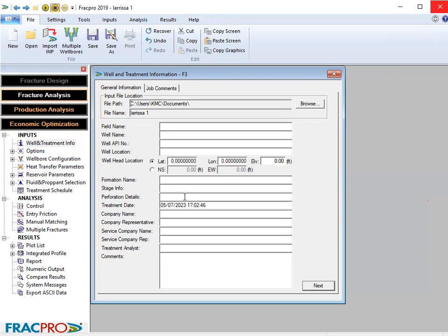Because under hydraulic fracturing well in Prosper, they'll ask you for the fracture height, the fracture width, the fracture half length, the fracture permeability, which will be part of the result that you're going to have. Once you generate that result, you see all of it indicated there. Once you have all of these parameters, you go to Prosper to generate your IPR. The model that you use now will not be the Vogel model or the PI model. What you use now is the hydraulic fracture model, and they'll ask all of these parameters. You input it, generate your IPR, and you now see that the well is functioning at a higher level.